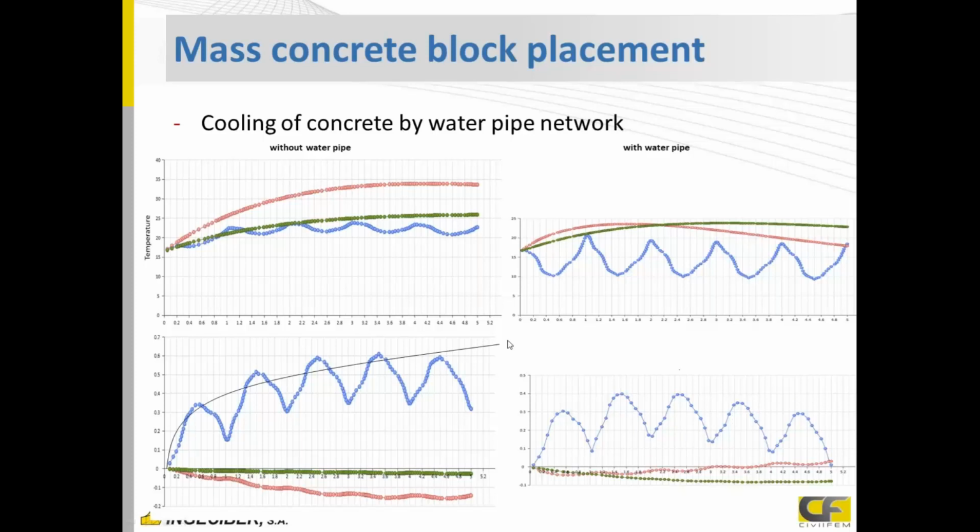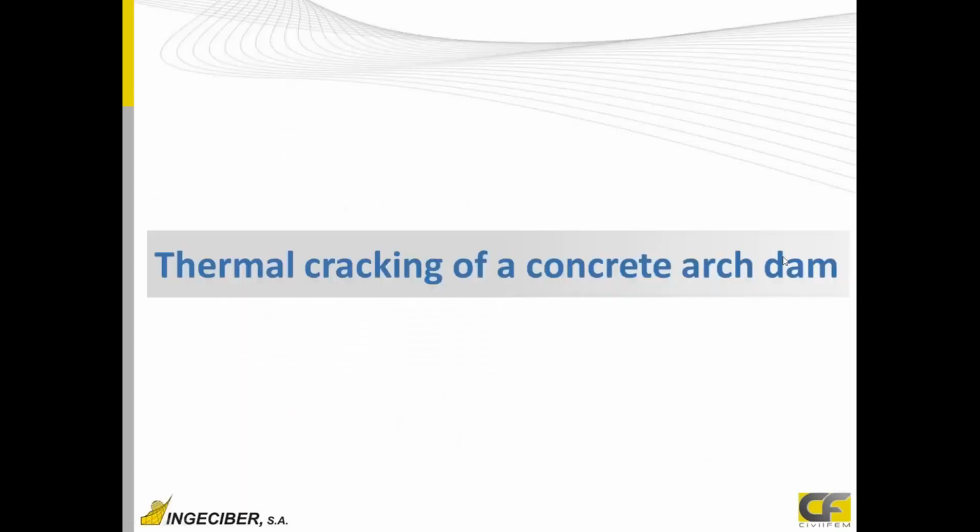So with this model, we can analyze with these capabilities any type of stresses due to concrete hydration, and residual stresses in the model. We could also use these stresses combining with structural stresses to design a model, for example a slab with a high thickness, and to check and design by code, considering residual thermal stresses and also structural stresses. So this is one example.